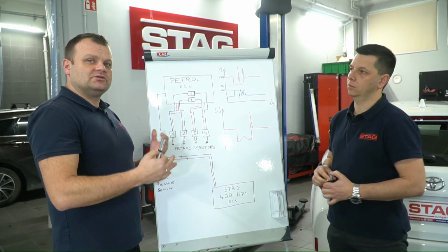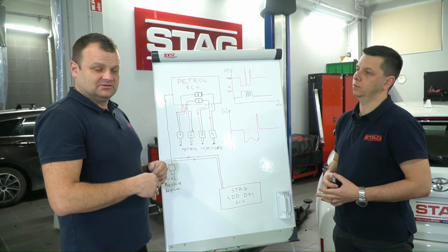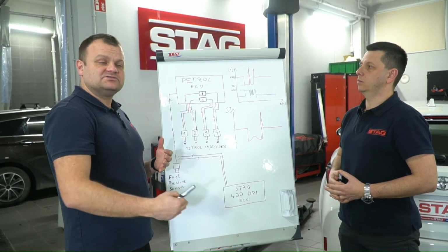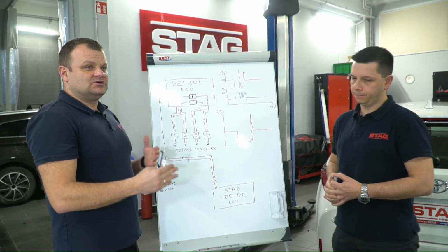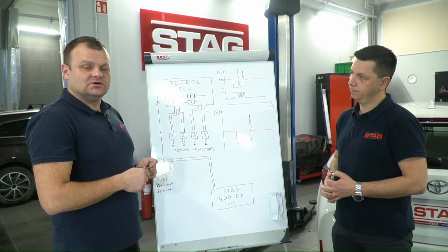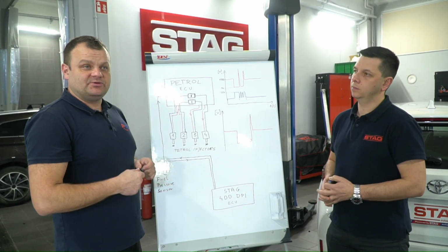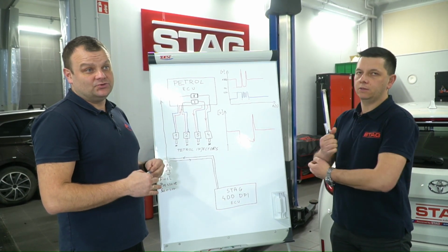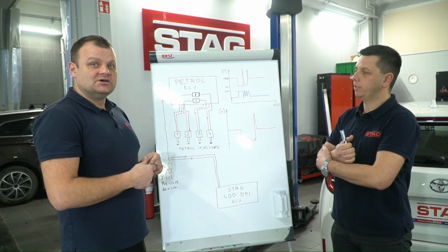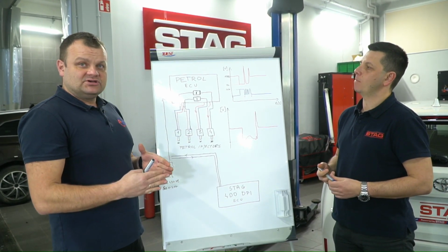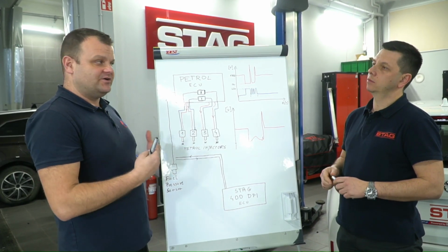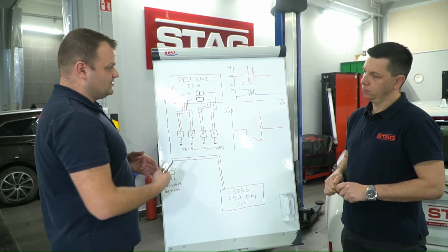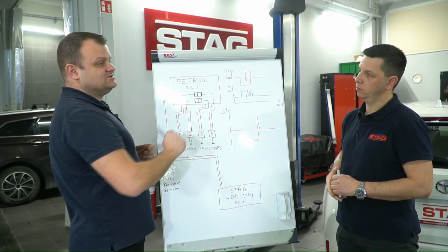Then when there is load on the engine, the RPM is rising, you press the throttle, accelerating. During changes of engine load, this pressure can rise up to 200, 250, and in new cars close to 300 bars. Right. So the petrol dosage is highly related to the fuel pressure, and the opening time is also important.